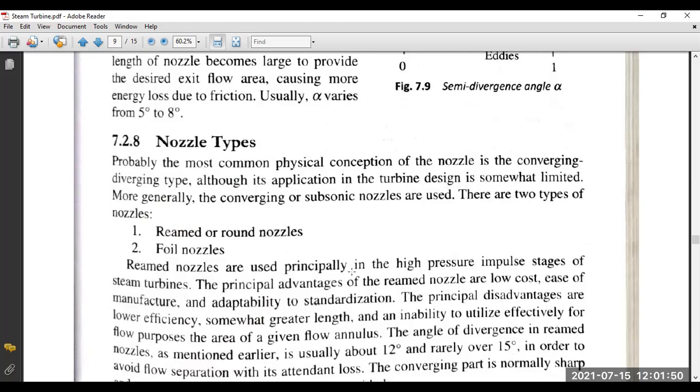The rifled nozzles, or nozzles with the formation of a screw helix inside, are generally used in high pressure impulse turbines, where we have a very high pressure, and by using the nozzle we can redirect this very high pressure from the inlet to outlet to a considerable extent, so that this high pressure is converted to high velocity energy for injection in the turbine blade itself.